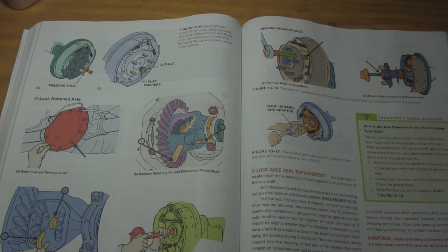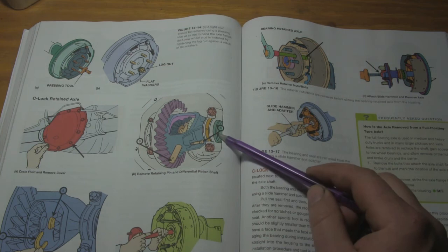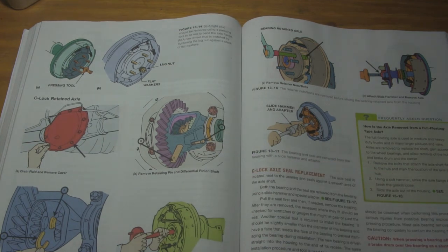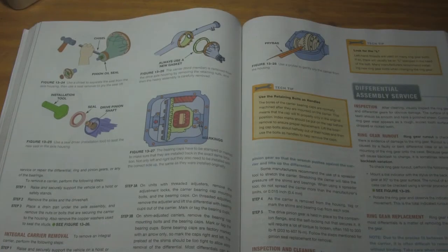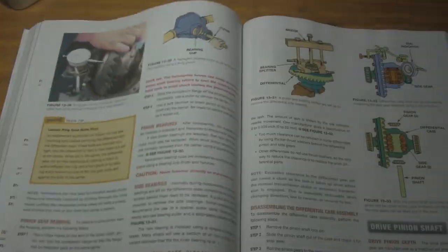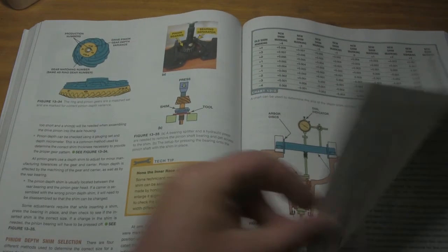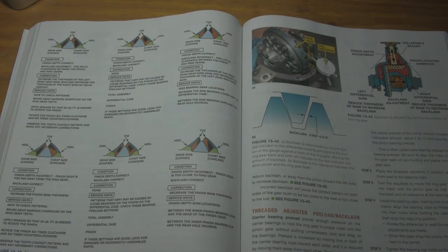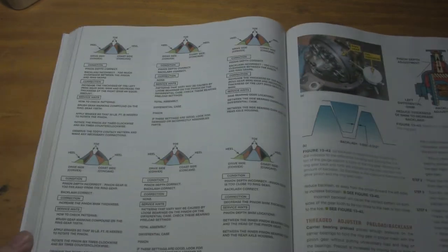And if you keep track of the old shims before you tear this thing down, and you pay attention to how many shims came out of the passenger side, how many shims came out of the driver's side, you can use it as a reference when you go to reinstall the new components. And so it'll help you get set up faster, because checking gear backlash and checking contact pattern is critical. And in order to send an axle out, you have to have all those tolerances in spec. And so if we get into page 246, this is what I'm talking about.